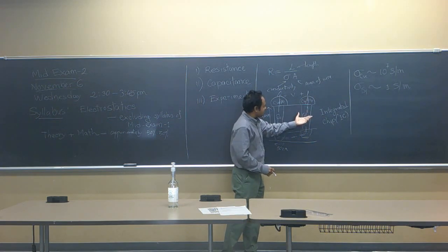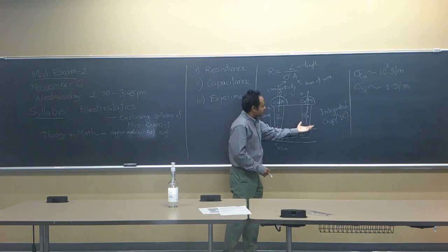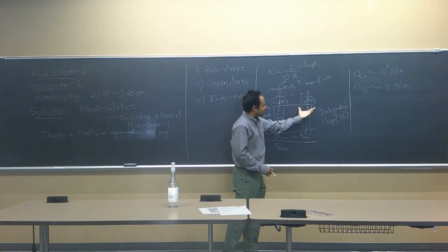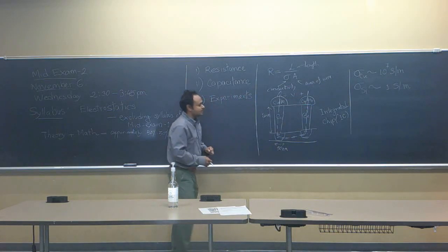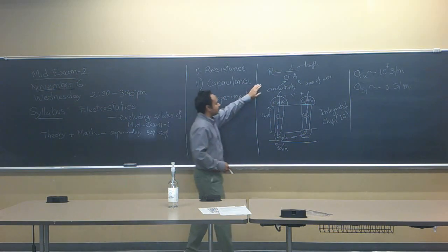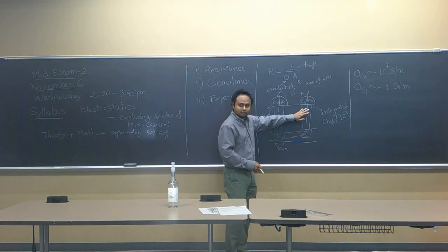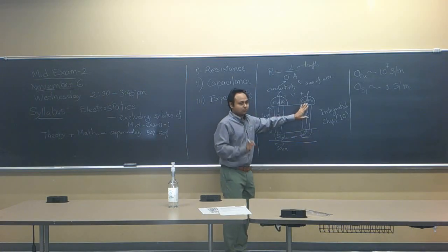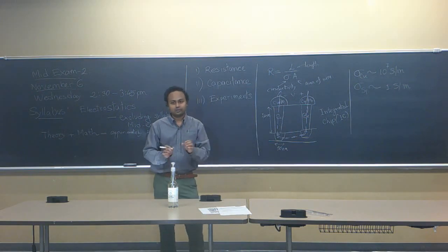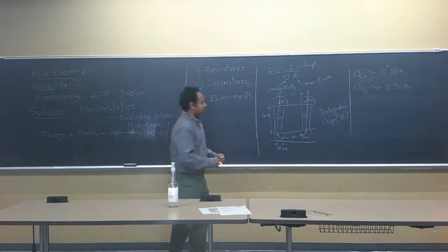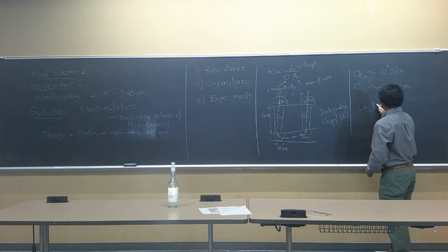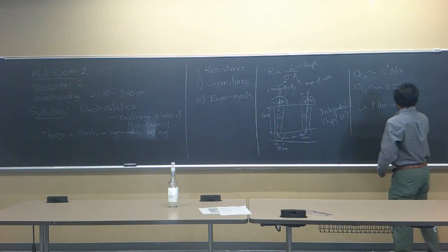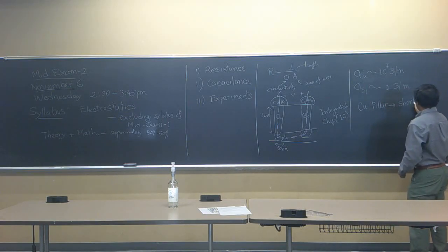First of all, let me ask you about the copper: how exactly do you want to design these things? Do you want to design it to be very wide or very narrow, very tall or very short? How do you want to design it in order to minimize the resistance? Wide and short. So it should be short and narrow? Bigger, wide. So the copper pillar should be short and wide.